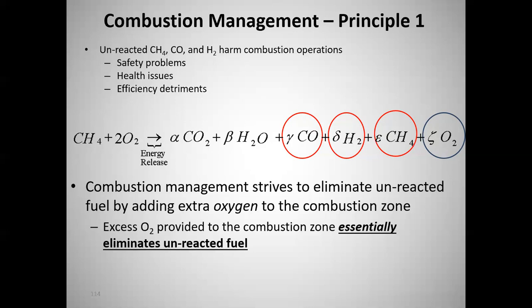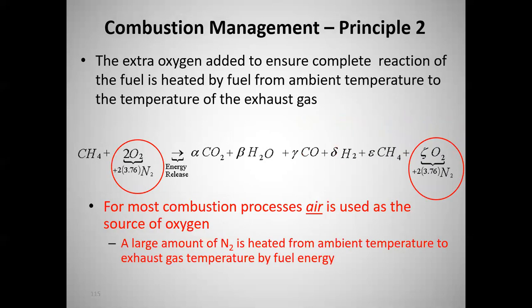These combustion management principles in this course are pretty simple. Principle number 1: put in all the air you need until you burn all of the fuel. That's pretty simple. Principle number 2: don't put in any more extra than you absolutely need. So be careful how much you add, because extra oxygen added to ensure a complete reaction of the fuel is heated by the fuel from ambient temperature to the temperature of the exhaust gas, and then it goes up the stack.